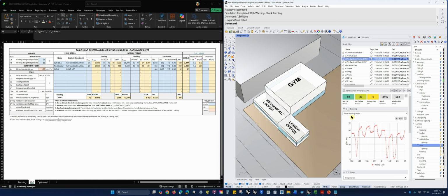And so then let's say that I'm going to go to the optimize. I'm using this configuration now. If I look at my peak heating load, like I was doing before, I've got a peak load that's much lower because I've optimized. And by the way, I think that these loads are maybe ridiculously low. I'm not saying that we're being completely accurate here. This is a process. The point is, though, that my peak load right now is for all three